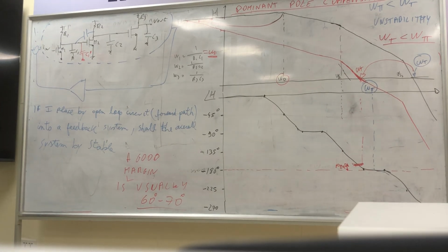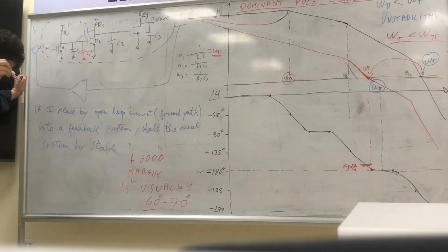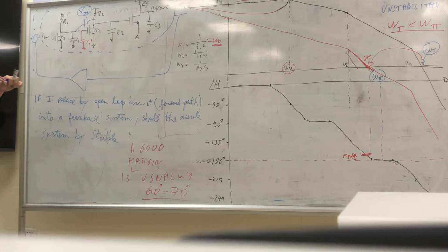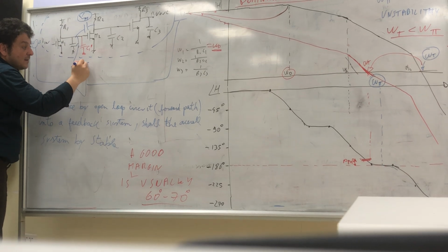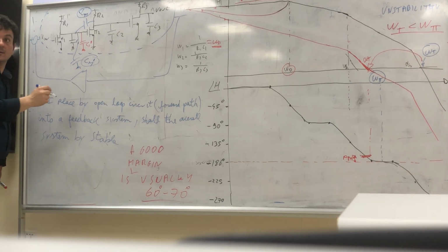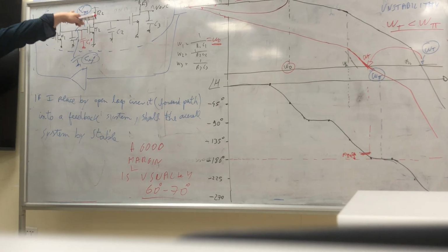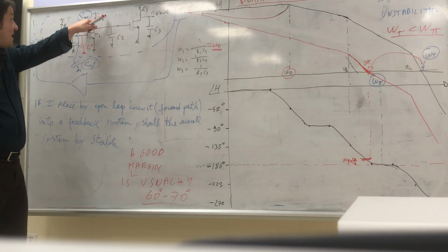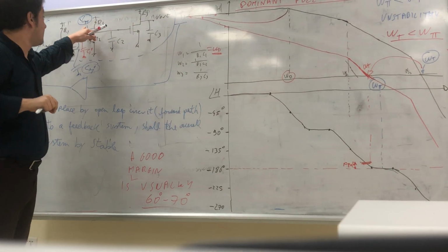If we add on purpose a capacitance here, Cm, what happens is that equivalently we can also consider a capacitance here, but exploiting the Miller effect. So it's better having the capacitance here than here, because in this way you can exploit the gain factor, and you can reduce the value of the capacitance you add.